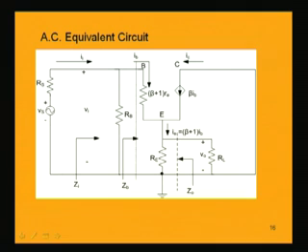The voltage between this point and this point, or emitter and ground, is equal to the current flowing multiplied by the parallel impedance between these two. In that way, it is very easy to understand. So, what will be this V naught? V naught is equal to the current I E into the parallel impedance R E parallel R L.